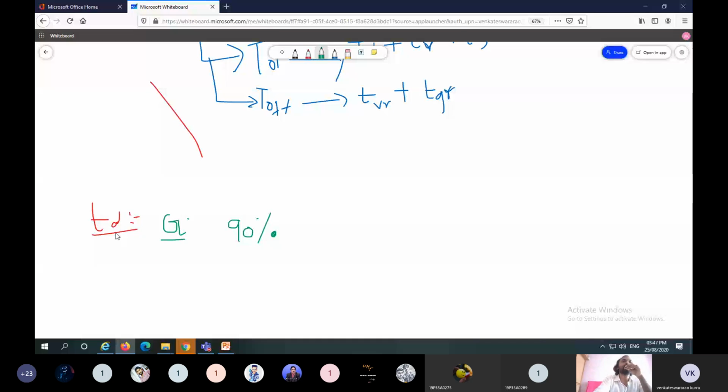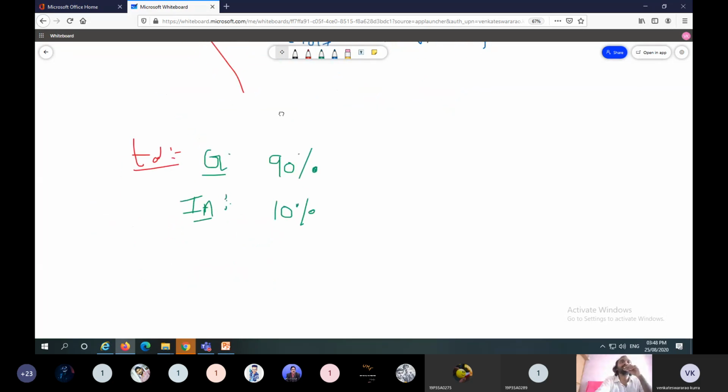In terms of anode current, it is defined as the time taken by the response to increase to 10% of maximum current. If the anode current reaches 10%, the time taken to reach 10% of maximum current is known as delay time. Next, in terms of anode voltage, VAK.